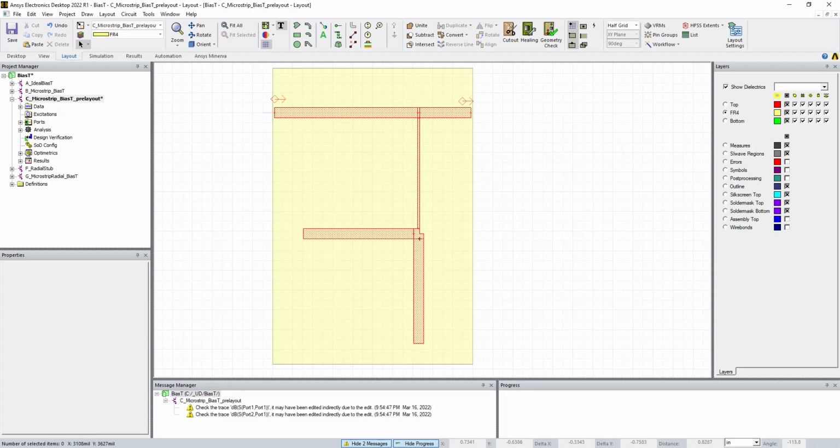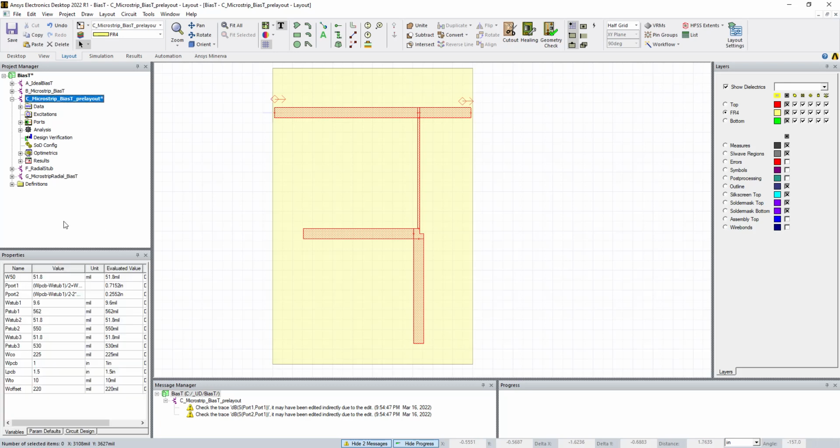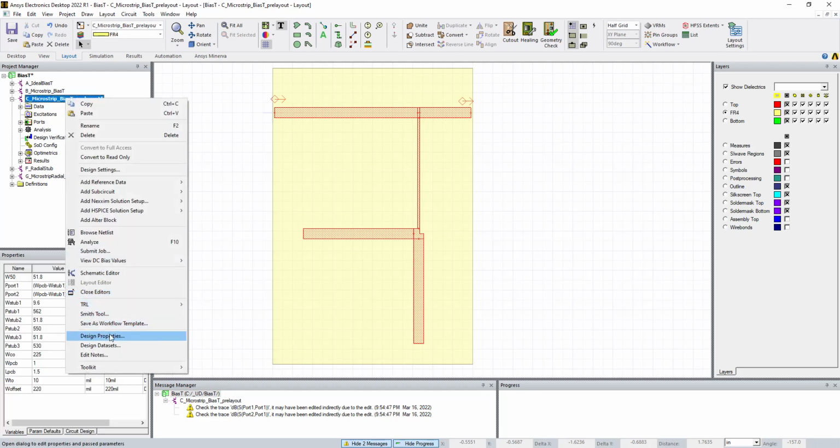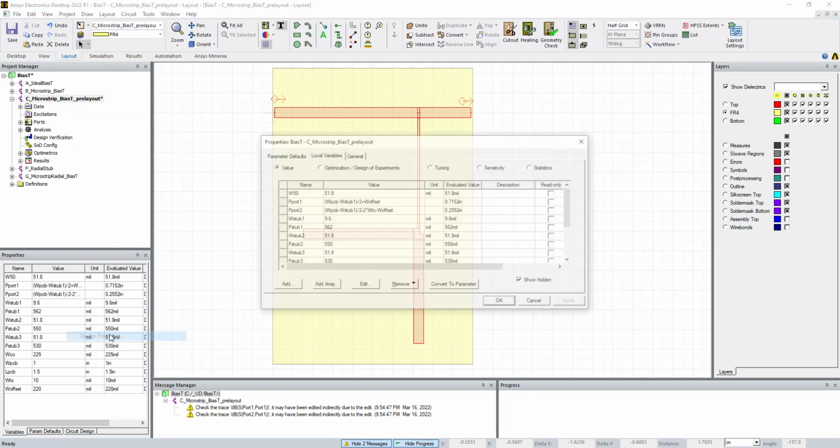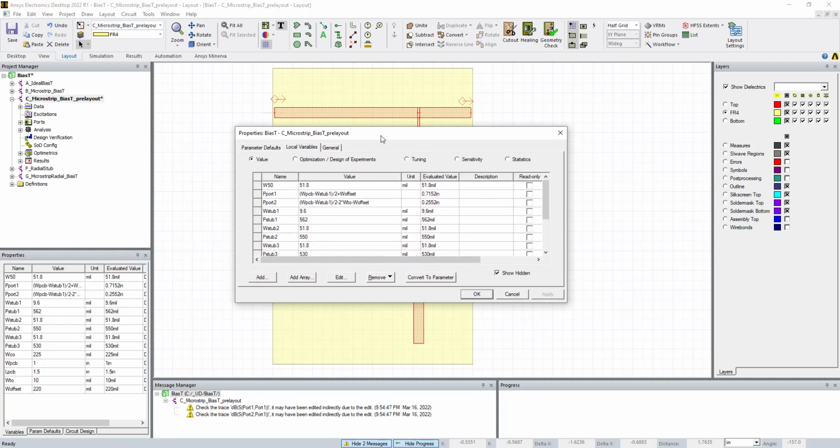From here to here is the width of stub 2. And from here to here is P of stub 3. So if I made the length of this printed circuit board and added up all of those variables, it would snap right to the edge of this board. And that seems very clumsy, but honestly, there's no real good way to do that from a WYSIWYG graphical thing. It's better just to type it in.